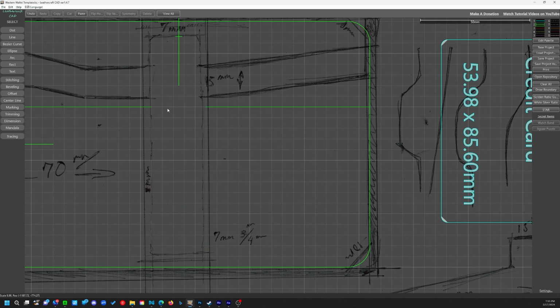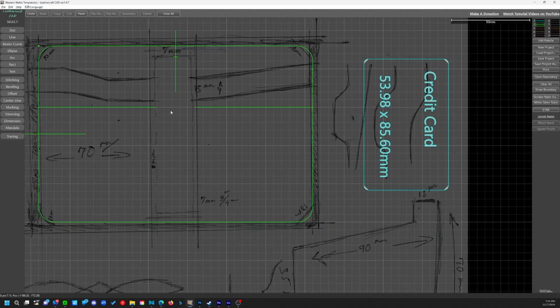Okay, so next, you can select this line here, and we're going to talk about a thing that's called symmetry. Symmetry allows you to actually clone. Basically, think of whatever you see up here in the top, it will reflect it based on whatever line you select. So I'm going to select this symmetry line. It's going to turn it pink, and it's basically asking me to select another line so you can have a symmetry. So let's say that I wanted to do this, it'll clone it up to the top.